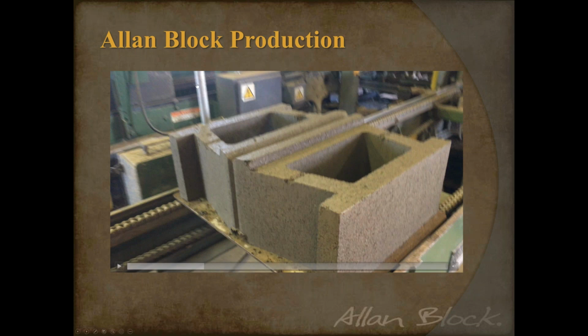And on the other side, you can just sort of see it here in the upper corner. Those blocks are coming back from the kiln that were produced yesterday, and they're going to come down and head to the left to the splitter. Because right now, these two blocks came out of the machine as one unit. There is no separation. But once they're cured, the knife blades of the splitter will come right down in this chamfer here, apply force, and eventually it'll crack the block apart. And those two blocks will be like sister blocks. They could actually be put back together like a puzzle piece, but you can never tell that from wherever they land up in the wall.